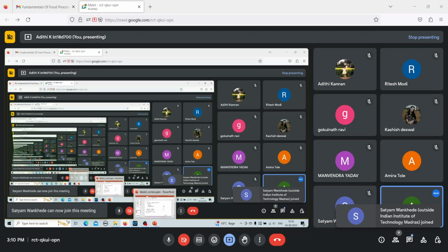So when you talk about relaxation or retardation time, it comes only for viscoelastic fluids, which means that the second term in the combination describes this parallel unit. Is this clear? The first term, sigma naught by E naught, describes the elastic part of the outside spring. Sigma naught t by mu naught describes the dashpot outside the parallel unit. The second term describes the entire parallel unit. And as you can see here, the strain is a summation of each and every strain.